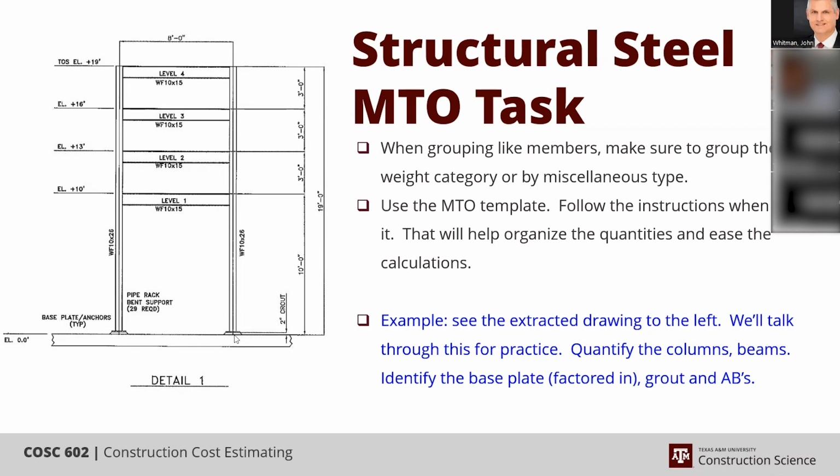On the assignment, there were some sections of some of the pedestals, and they were showing grout underneath the base plate, but we only saw it in section and not in plan. So I was wondering what the right way would be to quantify the grout.